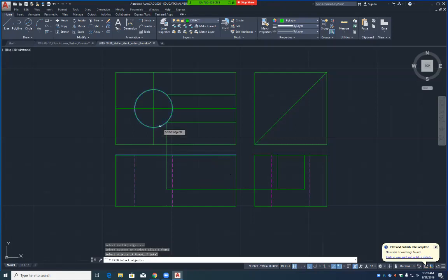Okay? Now we're just drawing it like we would normally draw it to begin with. These should be hidden lines, but don't worry because we're going to make them all solid. Is the front looking a little weird because we're doing a cross section cutting? No, we're going to end up cutting this out right here, and then you're going to draw what you see looking at this part of it right here. How about the front side? I'm a little confused on that. Should that be a hidden line on your front side? Right here. Yeah, and those two, yeah.